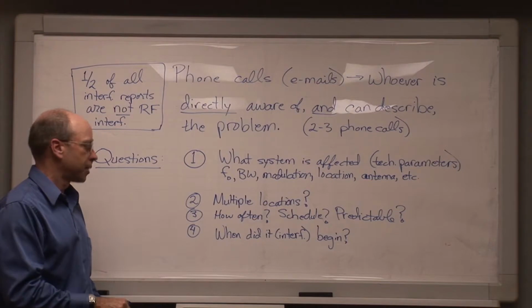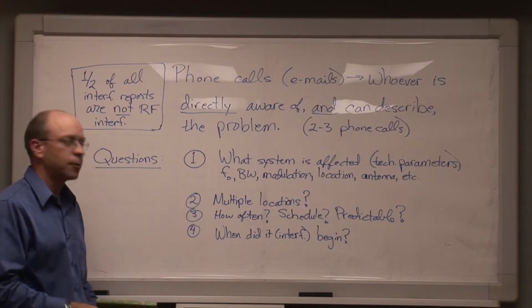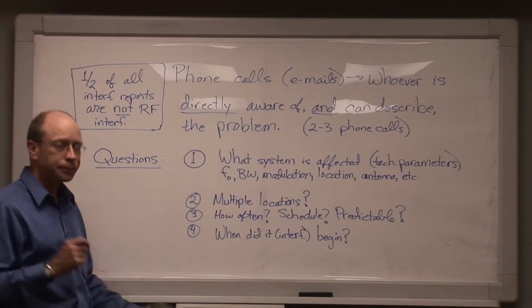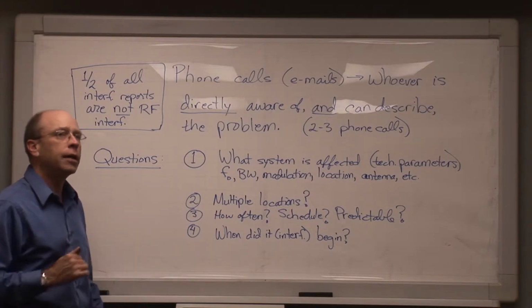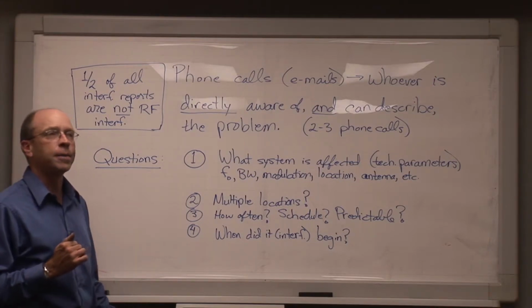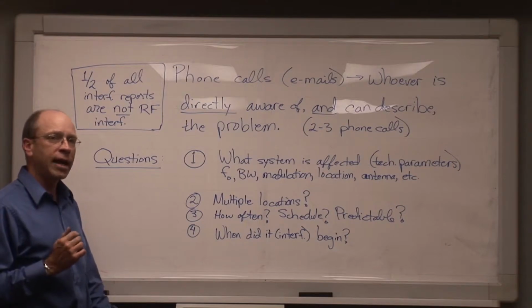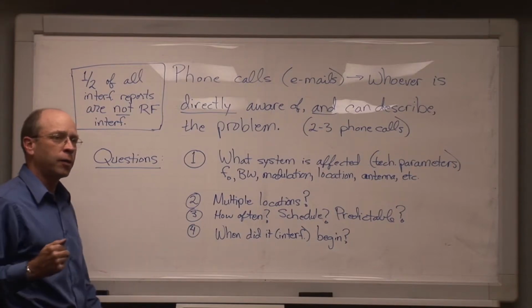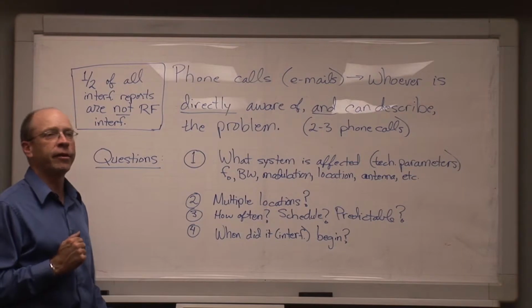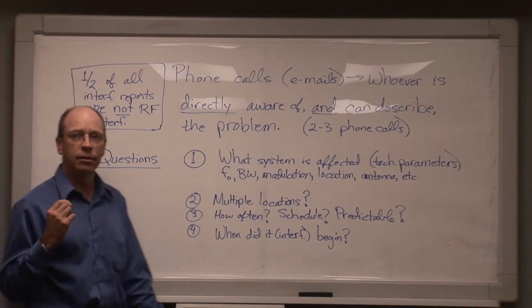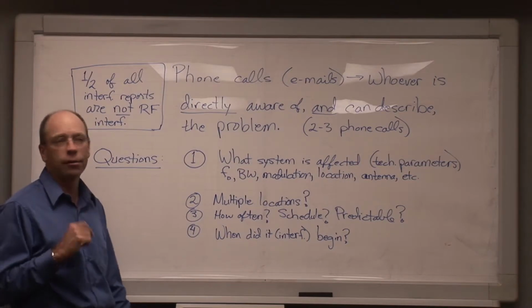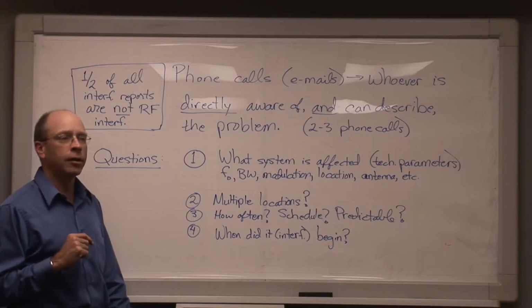We also had a problem years ago where a system transitioned from analog to digital. These were point-to-point microwave links sending telephone calls. That's not done much now, but years ago it was. And what had happened was when the analog point-to-point links were running between various locations, they were getting interference from various radar systems. But on an analog link, people just heard a little bzzz, bzzz every so often, and nobody thought anything of it. Later, they converted to a digital link.